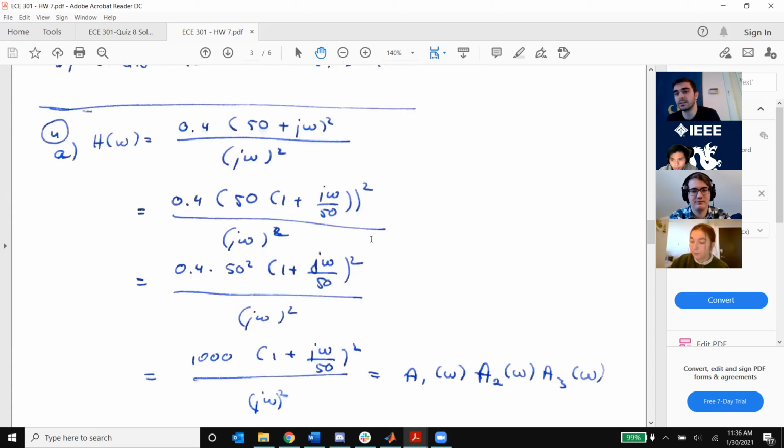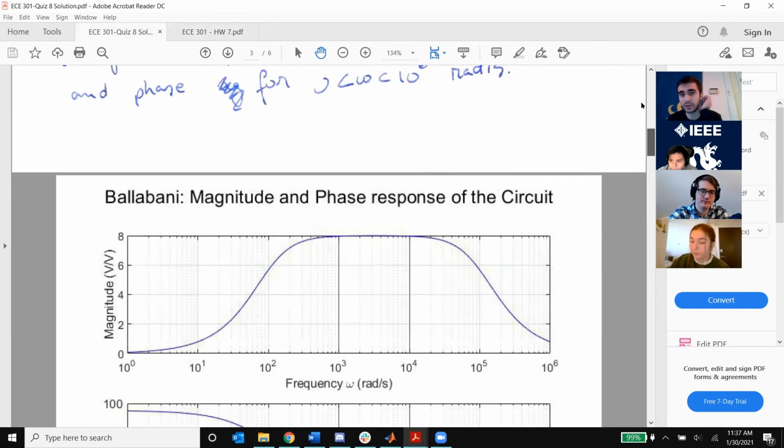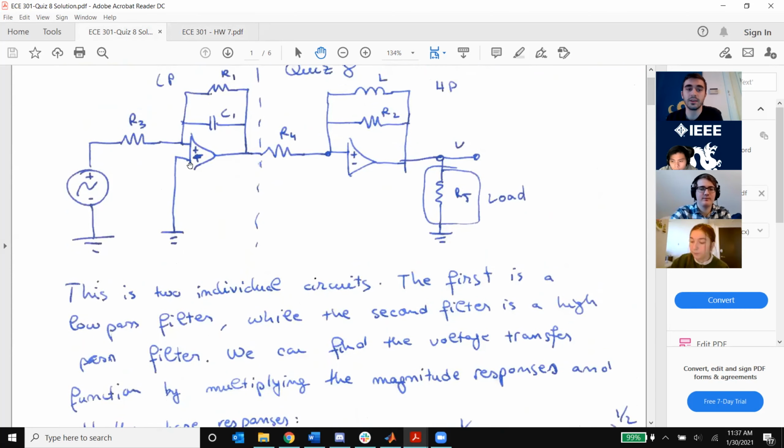But in signals, we have a more formal way of dealing with them, usually called transfer functions. So, for example, in this circuit up here, these are op-amps, and this is called a low-pass filter, and this is called a high-pass filter. So the idea is that when we have an RC circuit, if you remember from physics, or an RL circuit, we deal with frequencies, with alternating currents.